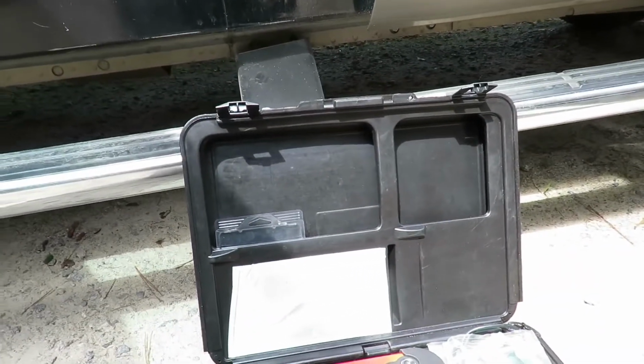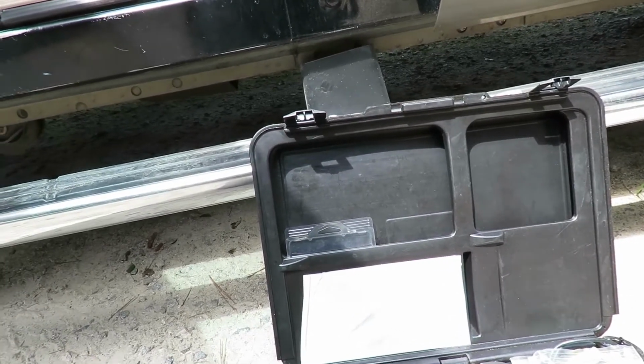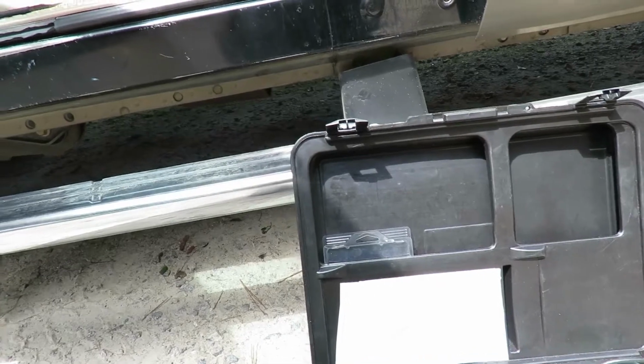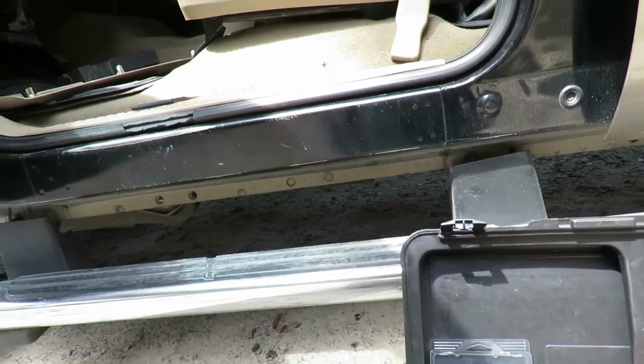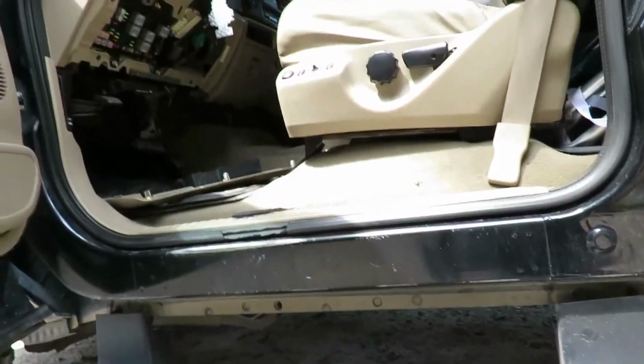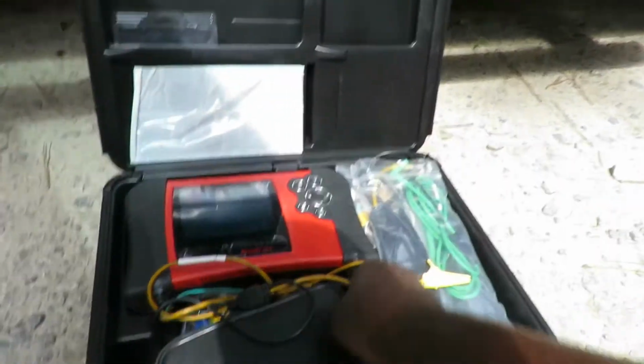Even though the truck is running, or even though your vehicle is running and the fuel pump seems to be pushing out, you can actually have good fuel pressure. And actually, if you have a scanner like the Actron or other scanners, you can check fuel pressure because this has an electronic fuel pressure regulator on it. So you can check fuel pressure actually through your scanner.